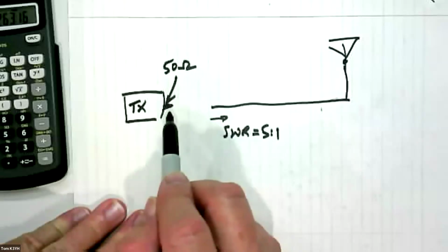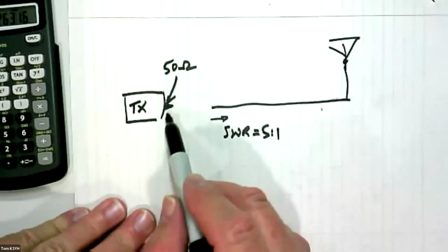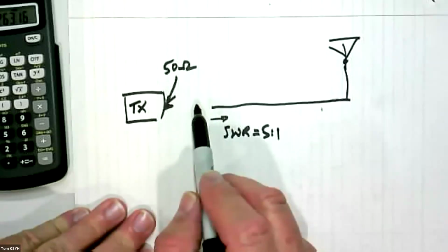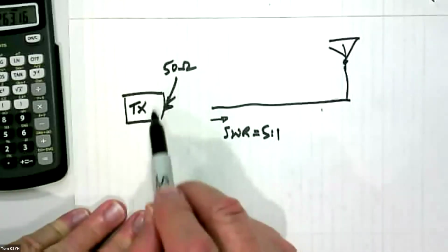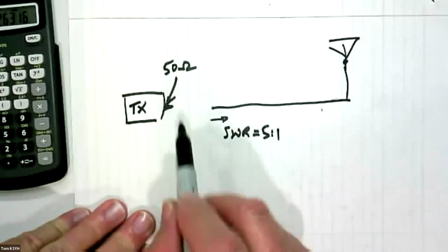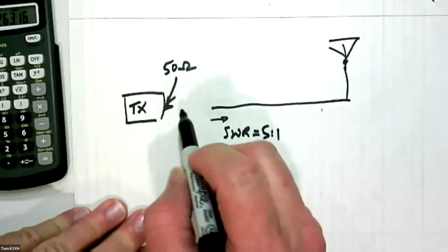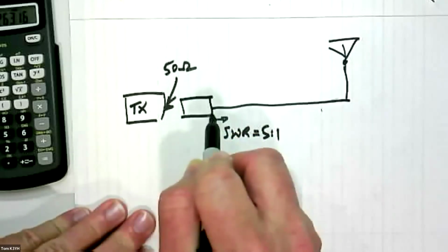He wants to connect to a 50 ohm load. If it sees anything other than 50 ohms, first off, you don't get maximum power transfer. Secondly, you could get significant voltages coming back that could hurt the transmitter, so it's got protection circuits to reduce the power. So just like I have at my house, as you've seen my jack, I have a box here.